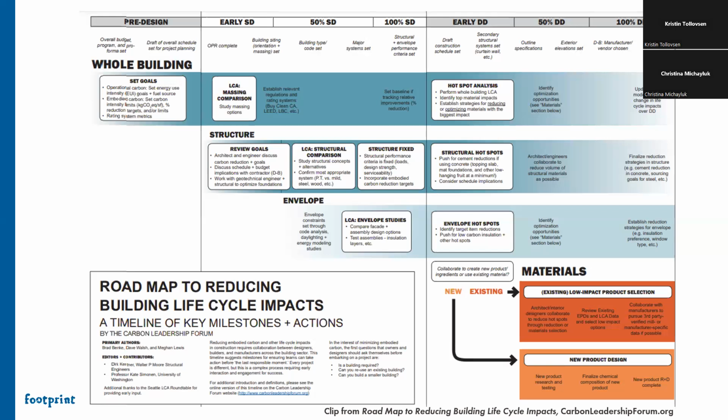But at the same time, depending on if you're going for a rating system, which one you're going for, there may be some flexibility in that. So with LEED version 4.1, we talked about that 1 point could be available just from conducting a life cycle assessment. So while ideally we'd like to get in and have opportunities for reduction, if you're a developer, or a client or owner that is new to life cycle assessment, and you're really curious as to what your projects are looking like, or what this building's impact would be, you can go ahead and do that at various stages of the project.